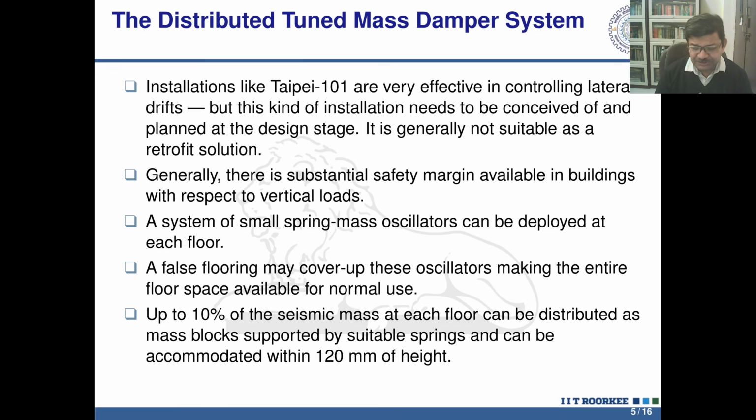So that gives us this idea that maybe instead of having one huge pendulum at the top, we can distribute small spring mass oscillators across several floors of the building, and they can be accommodated and tuned to the same fundamental frequency, or they can be tuned to different frequencies at different floors as per requirement.